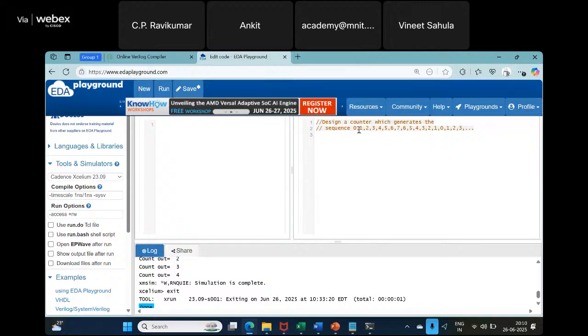See, another way to look at this is, there are two modes. I am either incrementing or I am decrementing. So one flop can indicate that. We can use one flop to indicate whether we are incrementing or decrementing, and the remaining 3 flops can sort of help me in the state part.